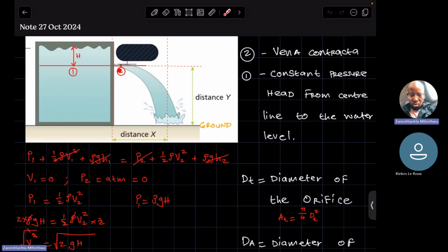Only when we look at the flow of the water ideally, not considering any losses, do we say that whatever findings we get are theoretical. So the difference between theoretical and actual findings is that with theoretical findings, we look at the jet, or the system being 100% efficient, meaning that we are not considering losses. Hence, we only apply Bernoulli's theorem, which is a mathematical expression, and whatever we get there will be theoretical.